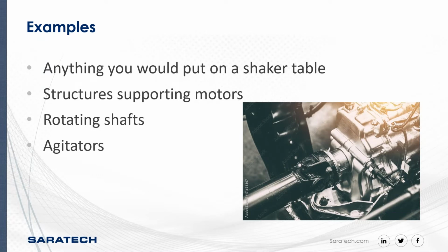Examples of this would be anything you would put on a shaker table is what you can simulate, but also the structures supporting motors or rotating shafts, agitators, for example, or anything attached to these structures are something that you can look at with the frequency response. Like I said, it is your peak response to a steady state sinusoidal input.